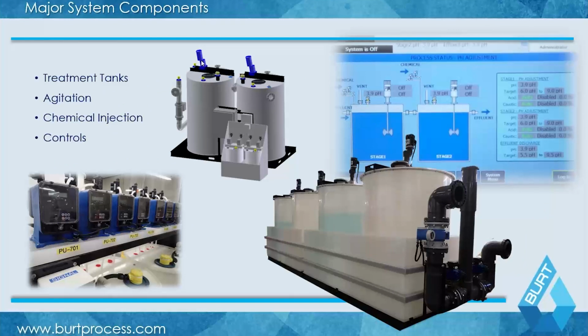The typical agitation rate as part of a system is approximately 2 tank turnovers per minute. And as your waste comes in and you monitor your pH and your chemicals are injected, you can basically achieve what's referred to as a well-mixed solution, which allows you to move the pH effectively about 2.5 to 3 pH units per stage. A little more custom designed, you can see here you have a 4-stage system. This is typically done based on room allowance. This is your typical chemical injection, which is achieved through chemical dosing and metering pumps.